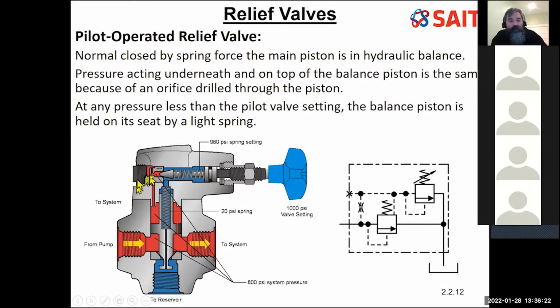The fluid, if it pushes through here, causing this to crack open and flow, actually wouldn't be this solid line here. I made a mistake there and I haven't fixed it this year. That would be, once again, a drain line, because now the fluid is no longer under pressure and it's a very small volume. It would actually be a small dash, short dash line correctly from here to this point.